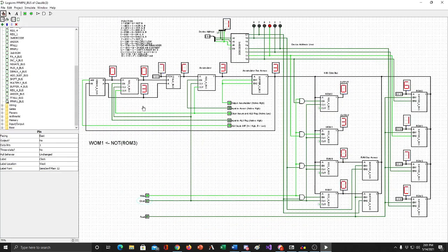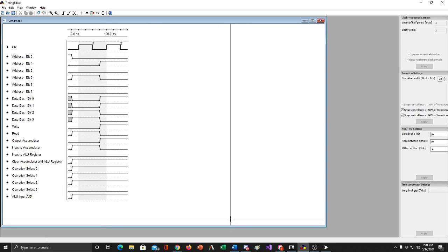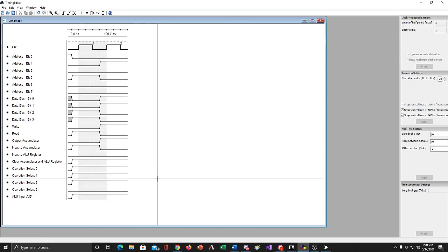Technically, at the moment, I think I left the ALU input on, so I could actually extend this all the way over. It doesn't matter at the second half because we're not using that information, but we loaded the information in. Then a number of things didn't matter, but what was critical is that we pointed to location 1. We wrote the value from the output of the accumulator into memory location 1. So that was the extent of the timing diagram. And so there are a couple of particular ones that I expect you to demonstrate as timing diagrams to show that you are following what it does.